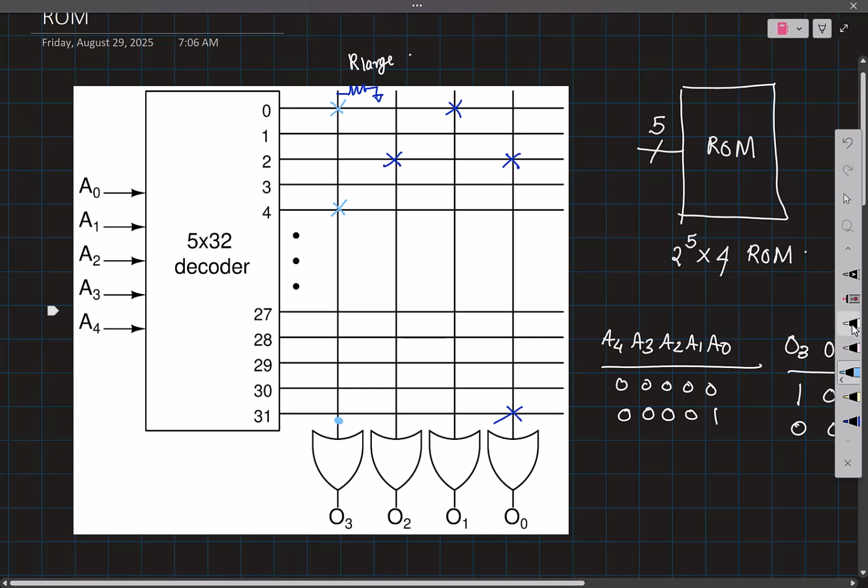So this model where you have shown a single OR gate here with a line like this will eventually get implemented by a line with some resistor connections in between these. So the decoder output has to be connected to this line using some switch, and you need to have a pull down path that is able to bring it down if nothing is connected to this line. That's all. Is the idea roughly clear? So as a representation, I will still use an OR gate here, but the actual implementation is going to be some sort of a wired OR.